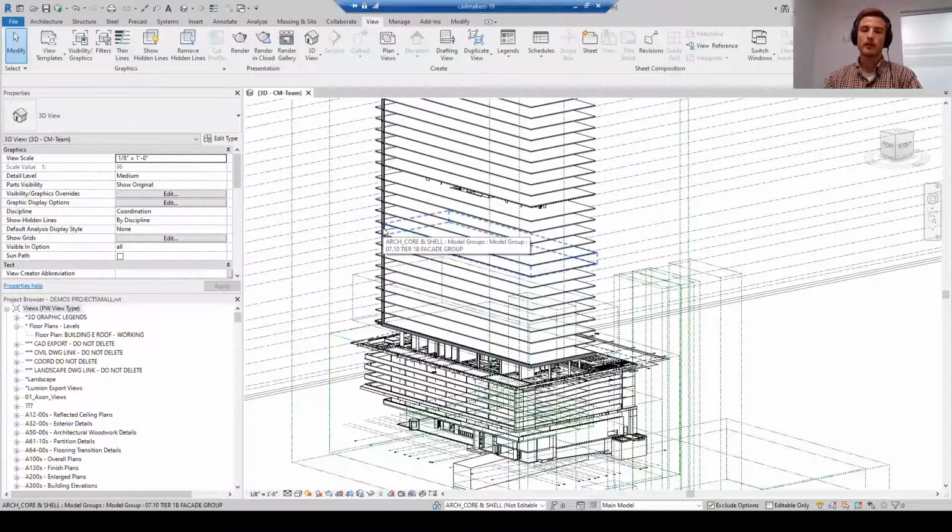Before you export, you want to look at the complexity of the model and what's going to bring value. The more detail you have in the export and it's uploaded into Builder, the slower the model will run. There's some pretty significant improvements we've made recently on the cmBuilder converting engine, one of which being chunking, which will allow our converter to break it up into smaller pieces and do them all simultaneously. Even that being said, having the architectural walls and all the MEPF fittings is just a lot of extra data and will not necessarily provide a lot of value in your construction simulation. So depending on the use case, we would definitely recommend filtering out some elements.